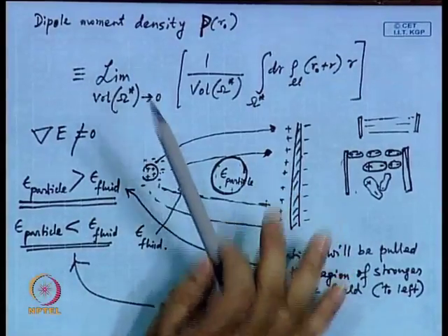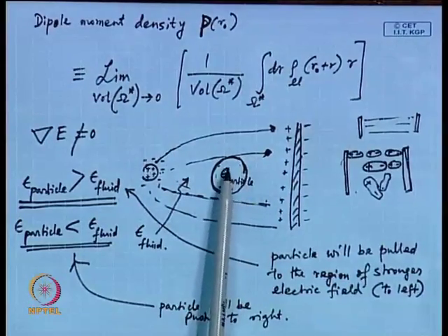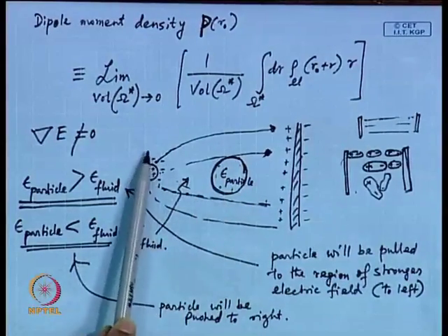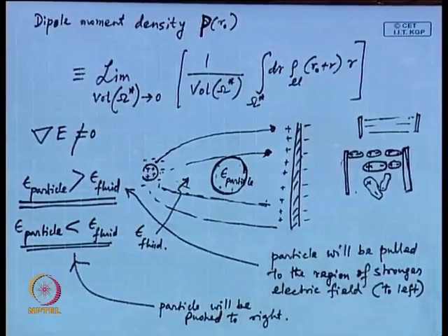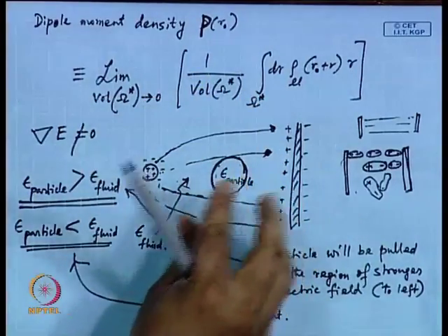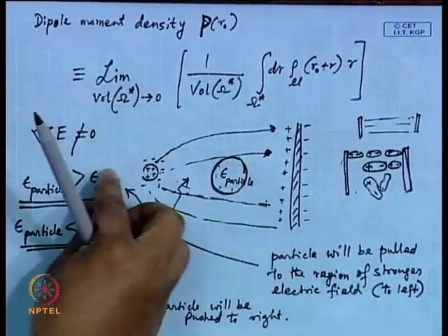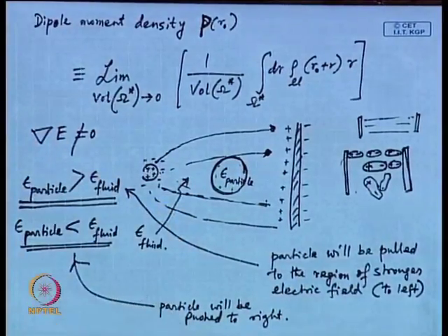The other possibility is the DEP trap that I said, that you trap the particle. Suppose so many particles are flowing through this, but some particles satisfy this condition, and those particles will be trapped next to the electrode. Once the process is done, suppose you have a sample, a slug, and you flow the slug through this place, and within the slug whatever particle satisfies this condition, you trap them next to the point electrode. This could be another way of looking at it, and this is referred to as DEP trap. Now, what is this DEP trap?